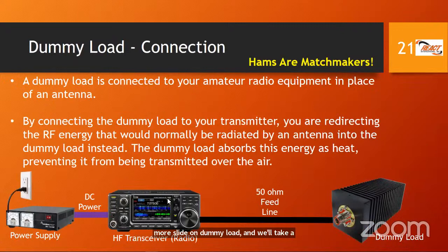All right, and this is just to show you how we use our dummy load, right? So we have our radio here connected to the power supply as before, but you'll notice that we replaced the antenna with the dummy load, and that's how we connect it. So we're doing some tests. We want to see if our radio is working well. Is it driving 50 watts, 100 watts? Of course, the dummy load needs to match the output power as well. So I wouldn't want to transmit 100 watts from this transmitter into a dummy load that is rated for 25 watts. No. I need to go 100 watts or more, right, to be on the conservative side.